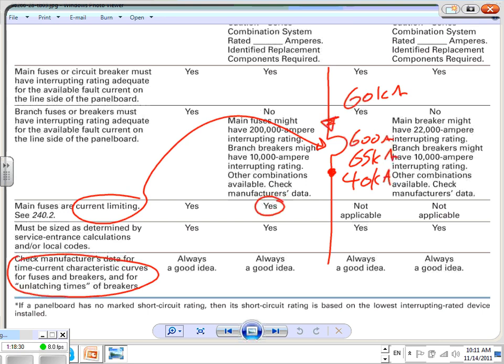It is a specially designed fuse, where as the current goes right through the fuse, it alters the chemical and the structural characteristics of the material, and it acts like a choke. It chokes the current and stops it. So look at this, 60,000 amp at the line side of the fuse just goes right through the fuse. This is, by the way, a fuse. When it goes right through the fuse it will choke it and only allow 40 kiloamp. Who cares?